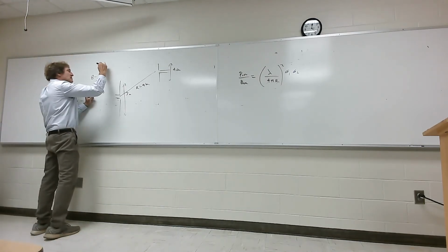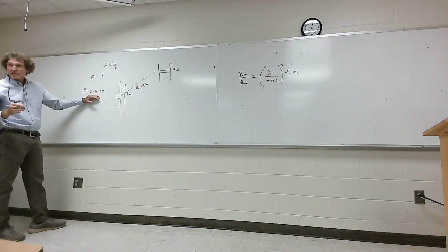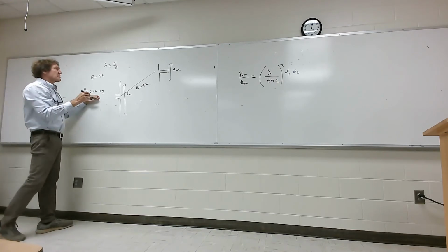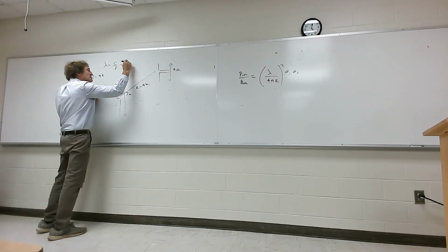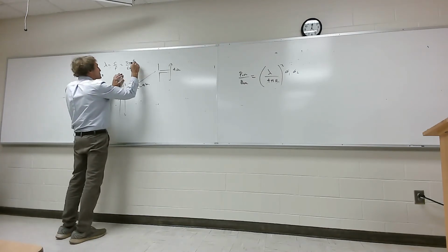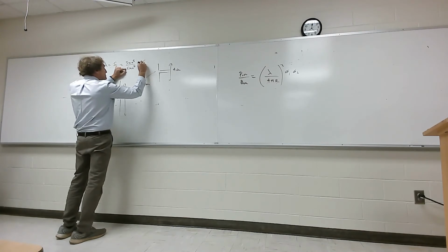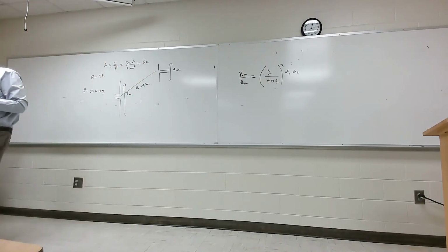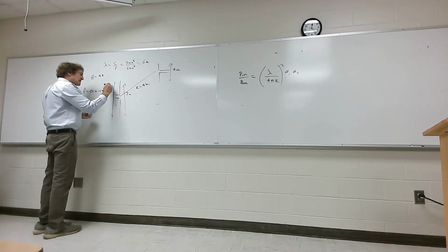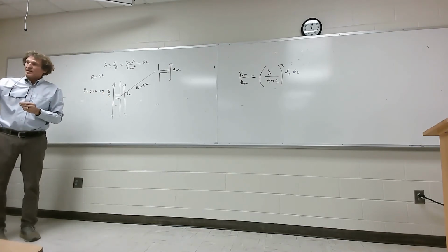All right, what's the wavelength going to be? It's c over f. It's 50 megahertz, right, class? All right, if it's 50 megahertz, this is 3 times 10 to the 8 over 5 times 10 to the 7, right? 50 megahertz is 5 times 10 to the 7. So that's 30 over 5, or 6 meters. Do you agree with that? If it's 6 meters, this is exactly a lambda over 2 length dipole, isn't it? Y'all follow me?